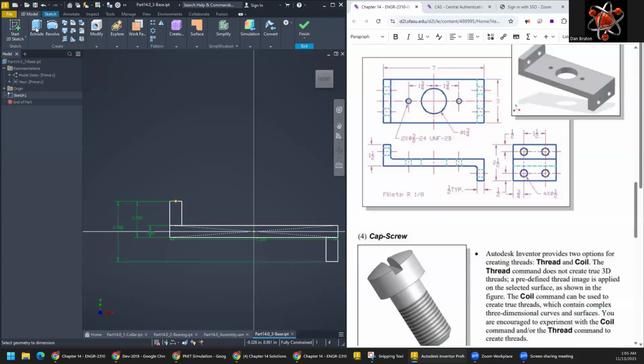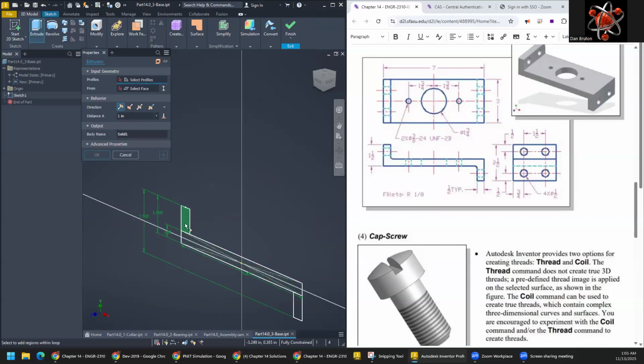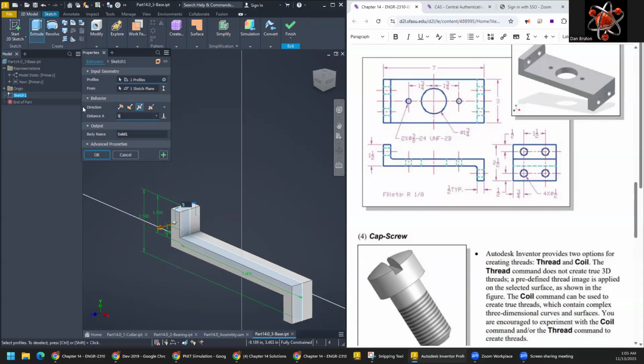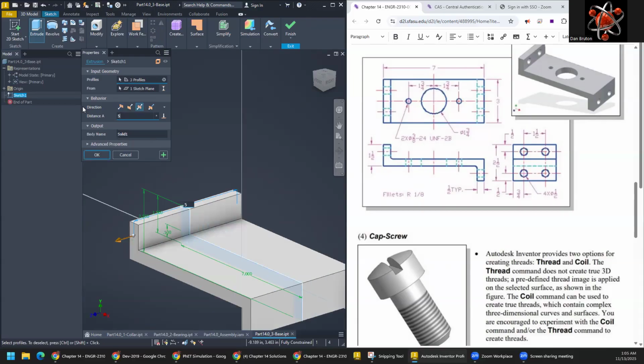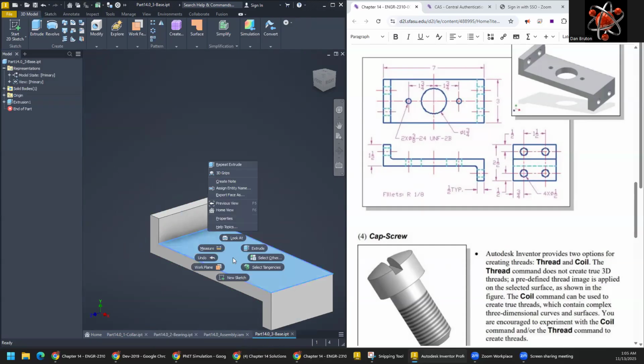And we'll notice that we don't really have to turn these lines right here into hidden lines. We could just select all 3 of them and do a bidirectional extrude, make it 3 inches. So we don't have to always convert visible hidden lines to visible lines, as long as we're okay with selecting multiple parts like that.